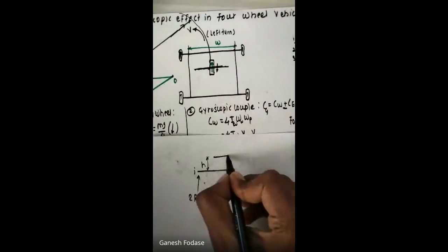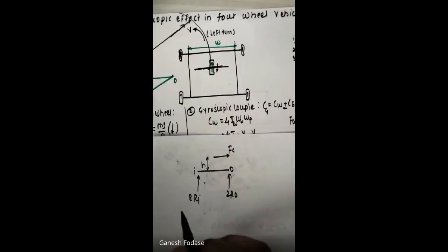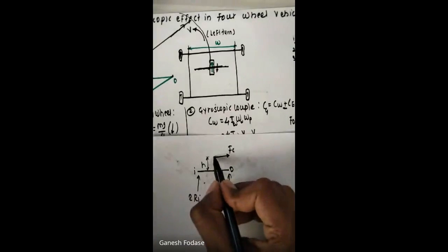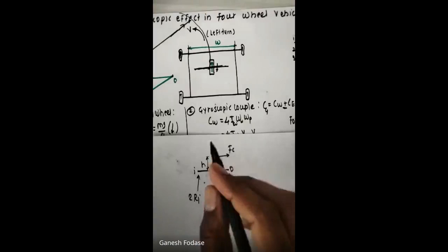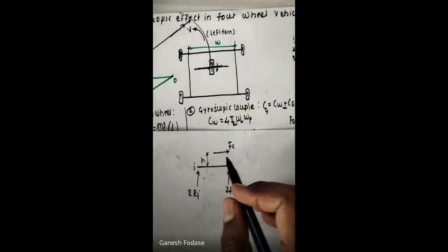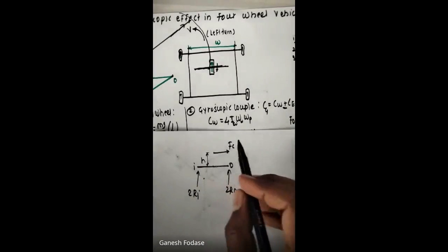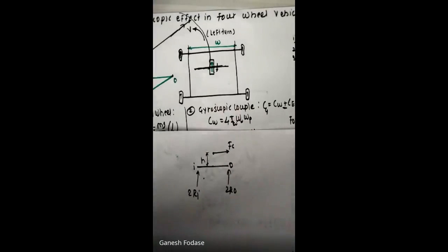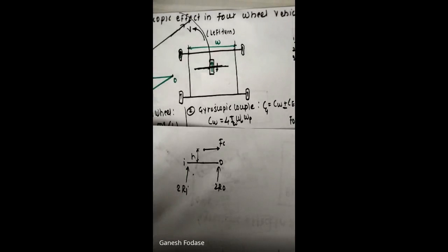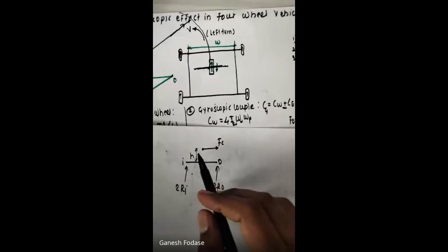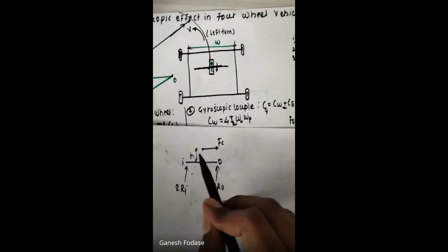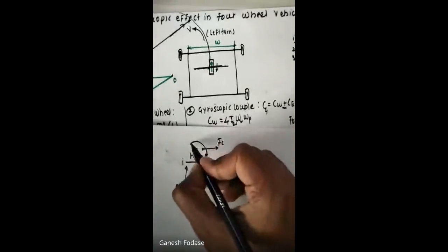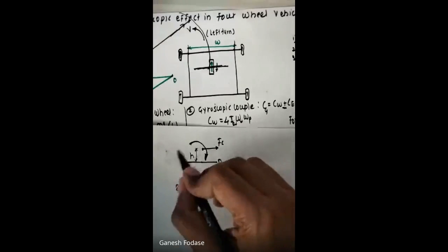And therefore, I can show here this is your centrifugal force Fc acting at a certain height h from ground level, where the Cg is concentrated, mass is concentrated. So if centrifugal force is like this and the height is h, how is the couple then? Is the direction of couple clockwise or anti-clockwise? The effect of couple due to centrifugal force will act like this only. Yes, and this is nothing but Fc times h. Yes, clockwise. I have shown it here.